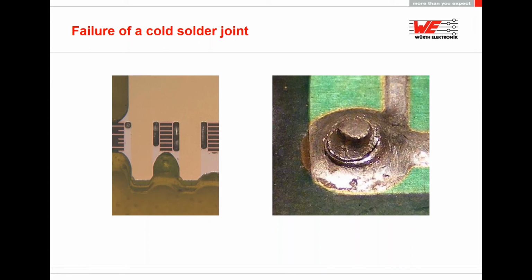You can also see it for our product group because we are able to manufacture bigger parts for soldering. We also would like to sell them, but it doesn't make sense. Also for SMT components, they are too big then. You are not able to pick and place them from the reel because they're too heavy. You need more heat in the soldering profile. So there are many points that don't really make sense to use these bigger parts for high current in a soldering process.